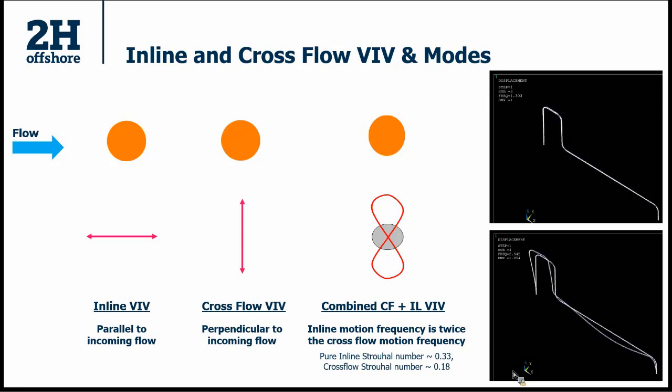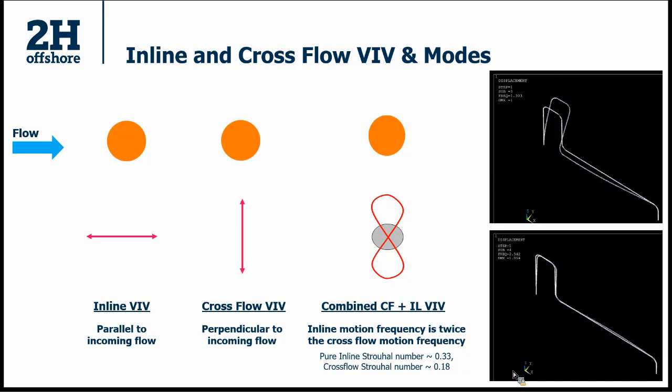Now, these are quite simplistic modes, but for a jumper, when you go to higher modes, like mode number 3, 4, and higher, the vibration is not that simplistic. The jumper has a lot of torsional and twisting modes, and you don't tend to see purely in-plane or out-of-plane vibration modes. That's where some of the challenges come in the VIV analysis of a jumper.